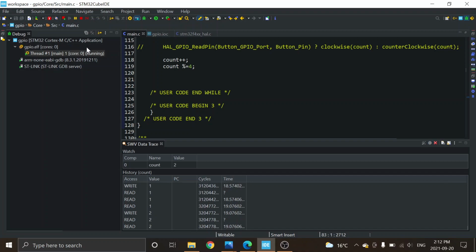Now, we are calling counterclockwise or clockwise or so on, and there's some delays in there. It's easy for you to fire out of the back channel far more information than it can display appropriately, and it'll start to give you some errors in the display, and it means you're overflowing it. It can't keep up with the amount of data you're asking. So usually have a delay of some sort. Don't just pump it at as fast a speed as you can get. Okay, so that was that part of it.